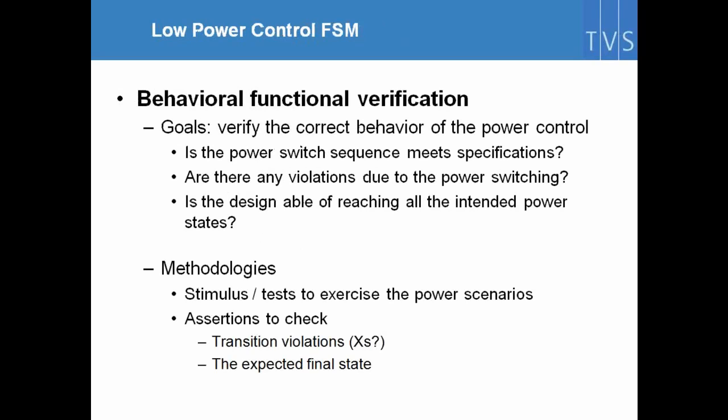In terms then of simulations, there are use cases that you really need to run. The first thing is to verify the low power state machine. We need to verify that the state machine is actually able to reach the different power states we are targeting.